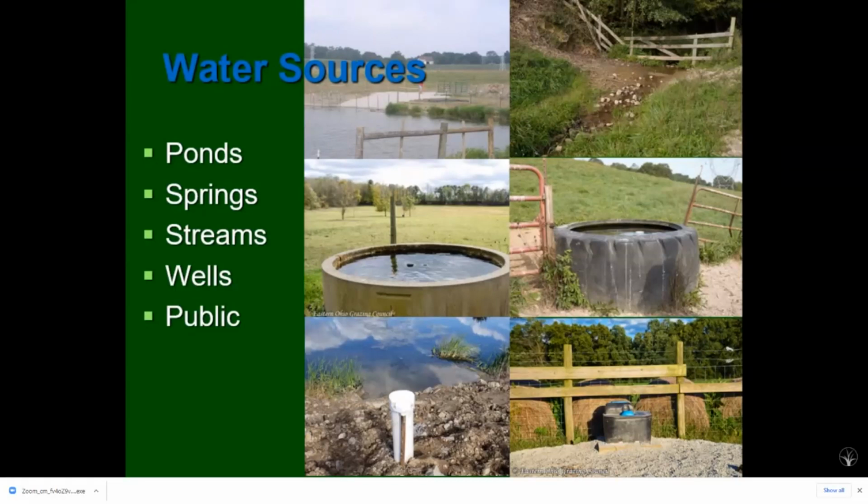And that's a problem with springs in general, developing a bunch of springs, is that springs don't typically happen in places where we want water. Here in eastern Ohio, we have lots of uplands that are as grazable as good pasture land, and our springs typically are down the hill and near a stream of some sort, in some kind of environmentally sensitive area. So if I'm working with a producer and we're looking at a bunch of springs, I like to be able to develop one good one and pump it and put it into a pressurized water system.